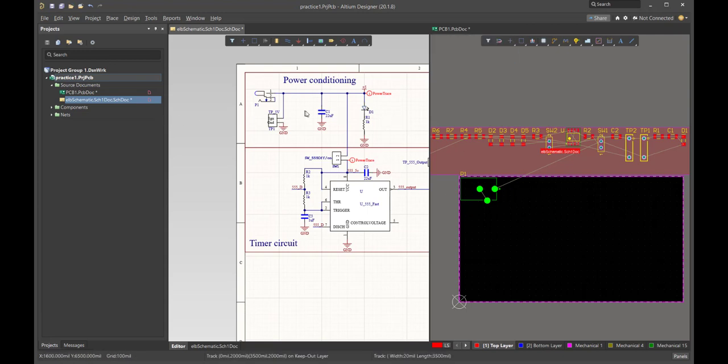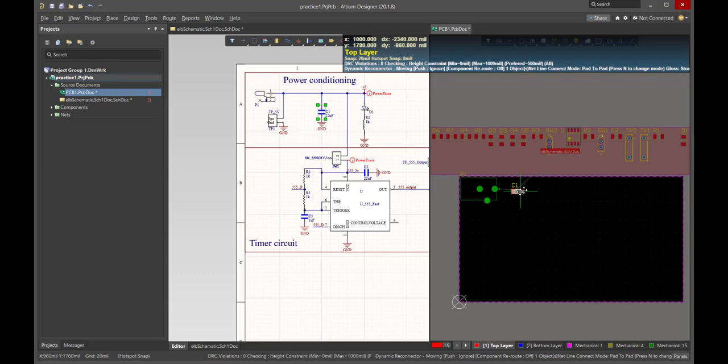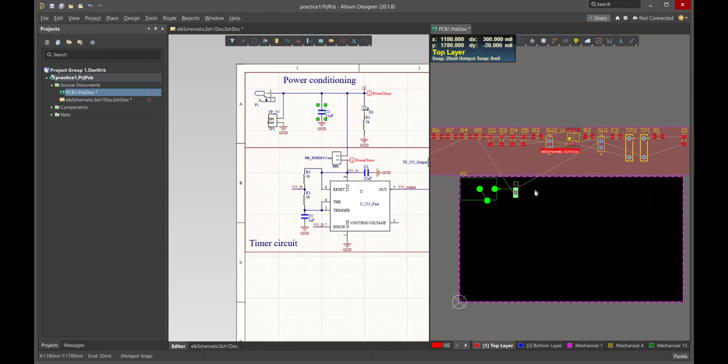So we've got our filter capacitor. Let's highlight it. And here it is on the layout. So here's our capacitor. We're going to grab him, and I'm going to rotate him around a little bit. Now, it's not necessary to worry about the routing of the ground, because we're going to have a plane on the bottom layer for that. And I don't want that part too close to the connector, because after all, I'm going to assemble this by hand, and I shouldn't necessarily put the connector down first, but if I do, if I put the capacitor too close, it may be a little hard to get the capacitor down and do the soldering.